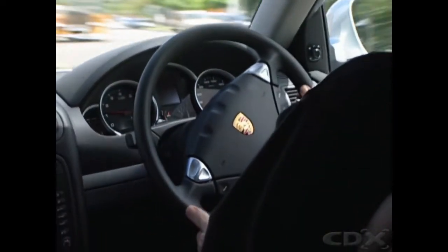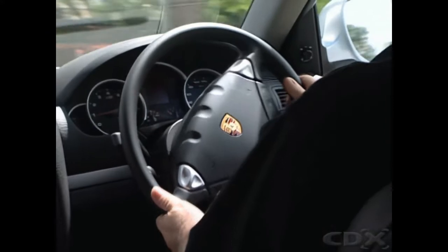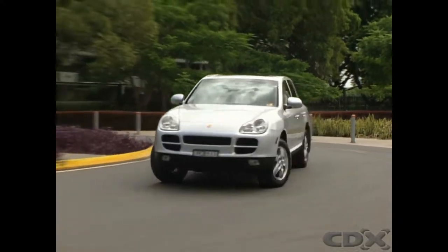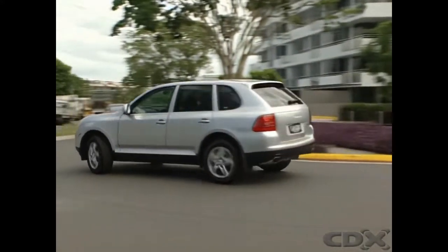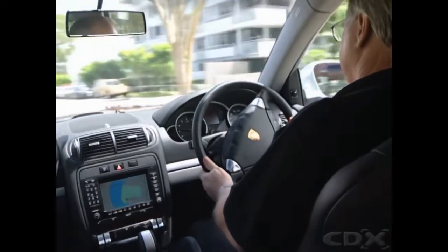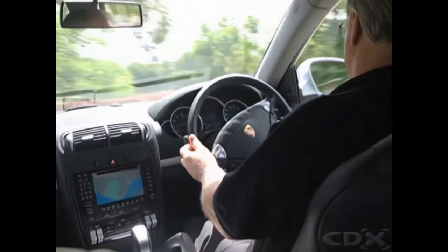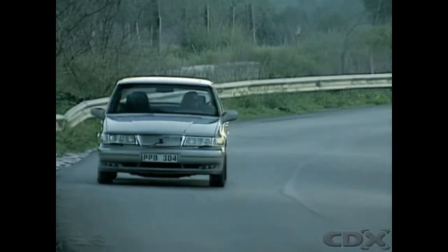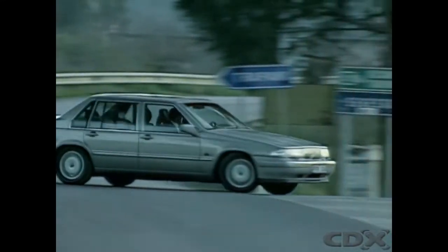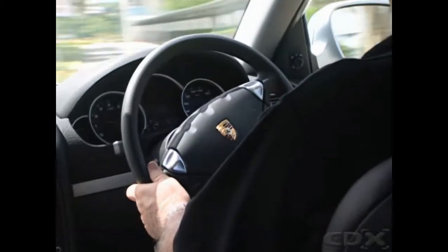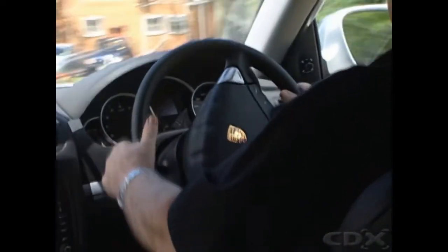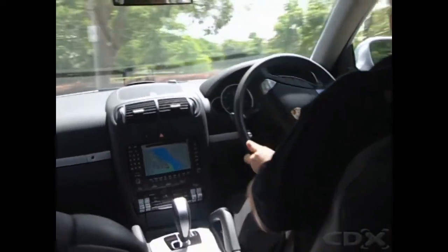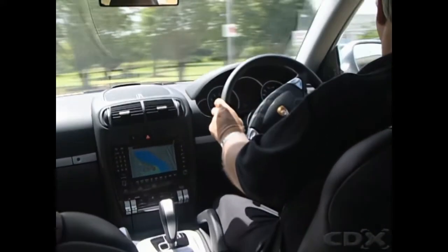Increased applications of front-wheel drive and wider low-profile tires places additional loads on front wheels. Steering then demands more effort from the driver. Power steering helps to reduce the additional effort needed. It's of most benefit during slow cornering and when parking. Assistance is provided as soon as the steering wheel is rotated in either direction, and it's designed so that even if system failure occurs, the vehicle can still be steered.